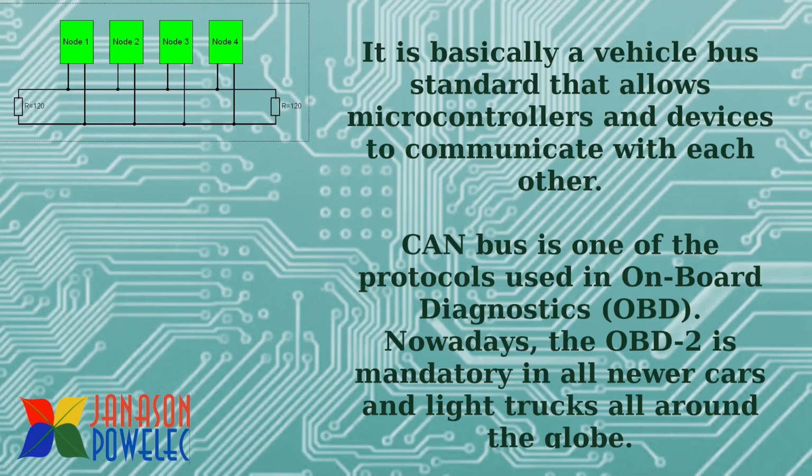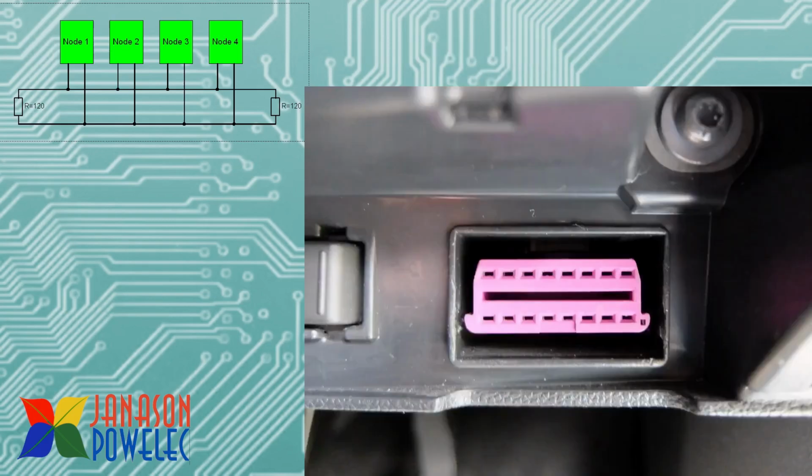So you may see some similarity between this CAN bus and RS485. RS485 also only has two wires, and the end of the bus will be terminated by around 120 ohm resistance. Similarly, CAN bus is exactly the same as RS485, and it is also terminated by a 120 ohm resistance at both ends. So this is the image of the OBD controller output.